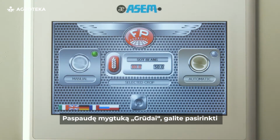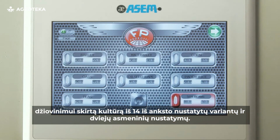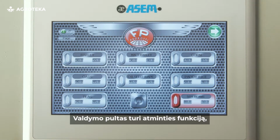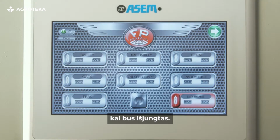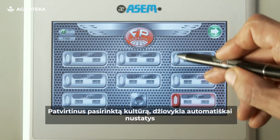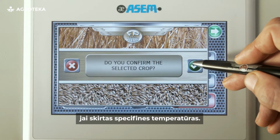By clicking on the crops button, we will be able to choose our crops kind to be dried amongst 14 presets and 2 personal settings. The panel has retentive memory, so it will remember your choices also when it has been turned off. By confirming the crops kind you've chosen, the dryer will set on its specific temperatures.